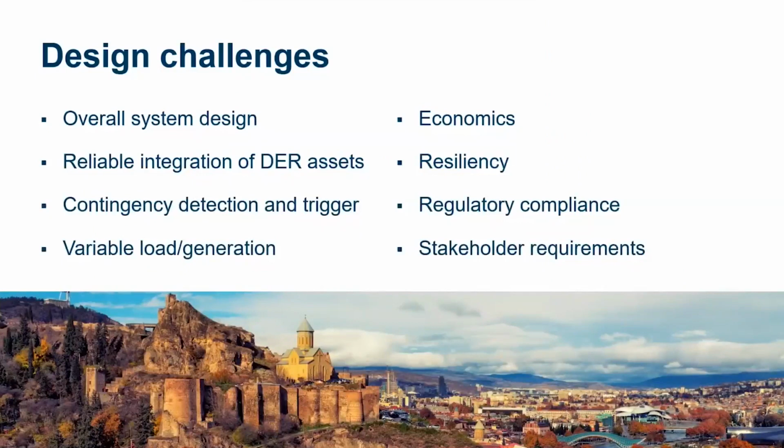The design challenges can range from identifying how the event detection takes place to regulatory compliance and fulfilling requirements for different stakeholders. RAS solutions may pose economic challenges in cases where there is a requirement for generation shedding and runback, and RAS has to select minimal generation to shed based on different generation assets available. For example, it may be more economical to shed wind farms compared to coal-based generation assets.